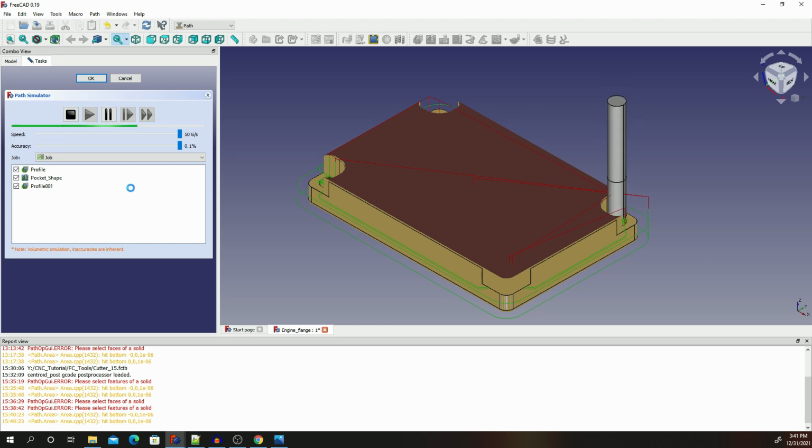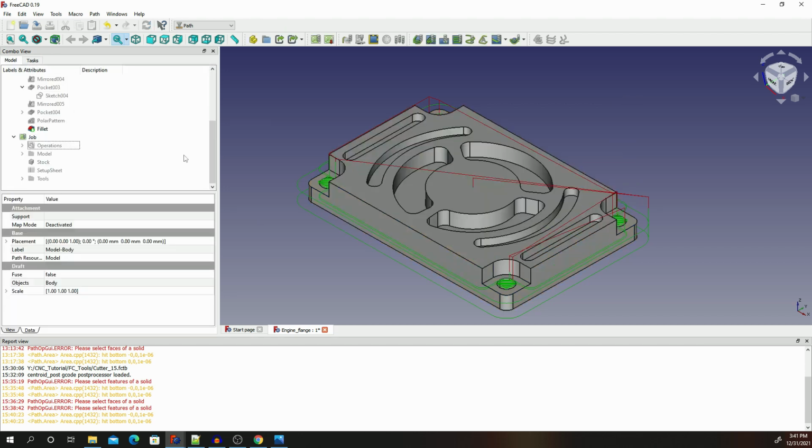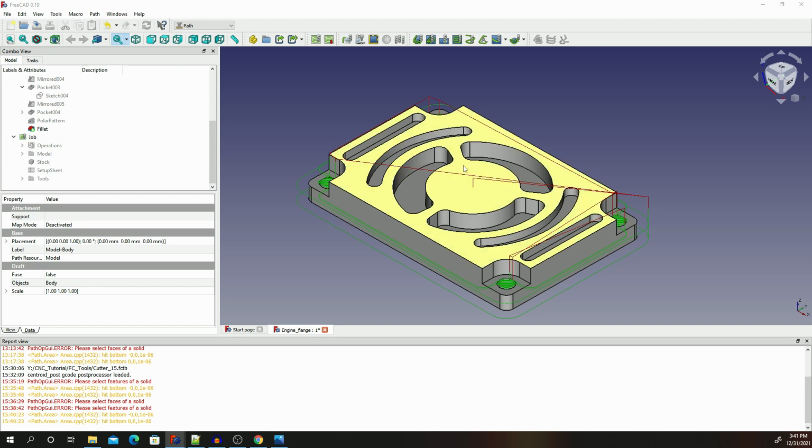So whenever you're creating these machining operations, make sure your operations won't cause a tool crash. Start with a process that removes most of the material while you go inside and create your part. So this looks perfect. Let's go ahead and go to another operation. So we finished that profiling. We are going to now create a pocket operation, and we're going to work on the 3 inside slots.